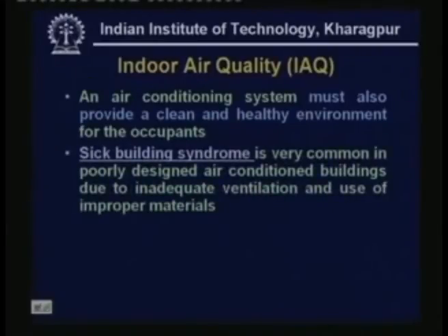As I mentioned, sick building syndrome is very common especially in places where the outside air is dirty, and the designer of the air conditioning system provides very little ventilation to save energy. Typically the indoor air quality depends on the amount of ventilation that is provided, the quality of the outside or fresh air that you are supplying, and also what kind of materials you are using inside the conditioned space. So these three parameters decide whether an environment is healthy or not.